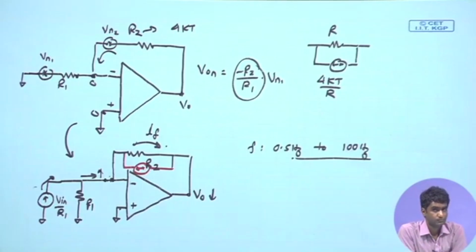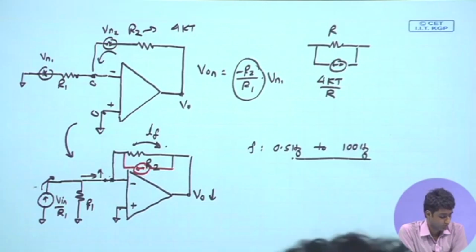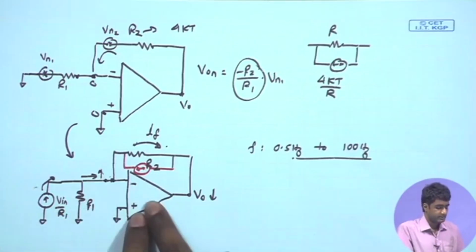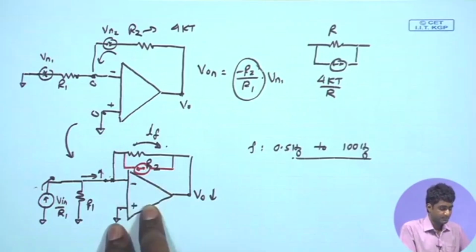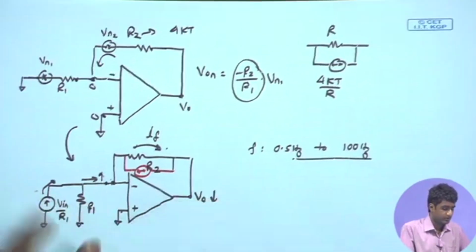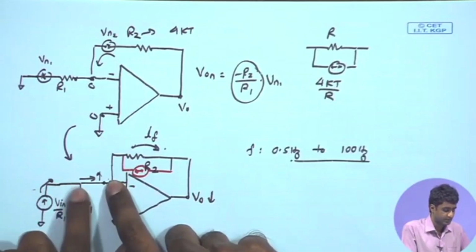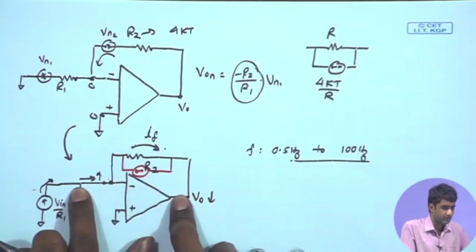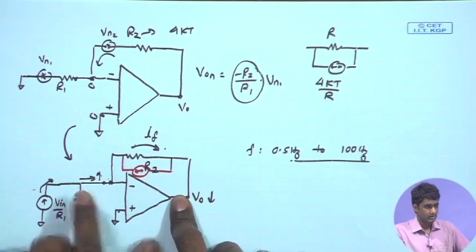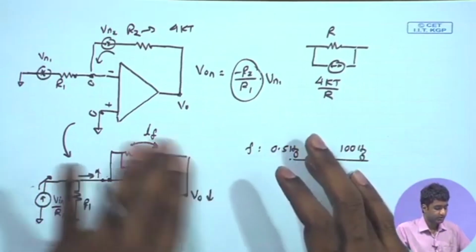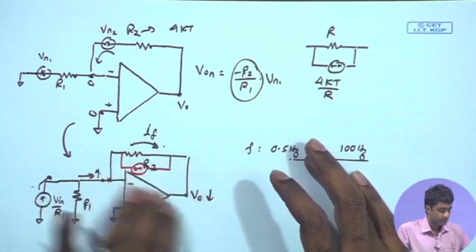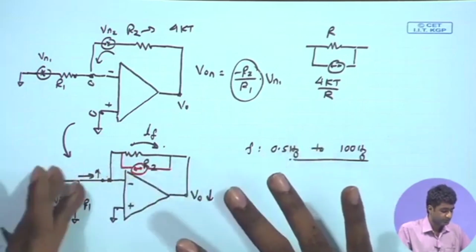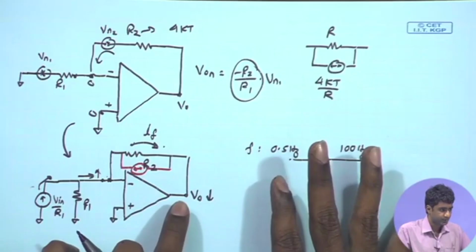Voltage across R1 is 0, so can we remove the R1? No, ultimately this is inherently a voltage to voltage amplifier. This op amp is a voltage to voltage amplifier. So, in order to amplify signal, you need a voltage over here. So, this current ultimately produces a voltage that produces an amplified voltage over here. But overall, this configuration is a shunt. So, this op amp along with the resistive feedback is implementing a current to voltage amplifier.